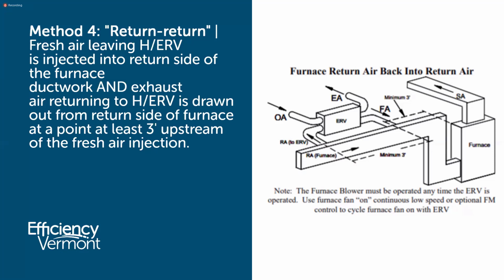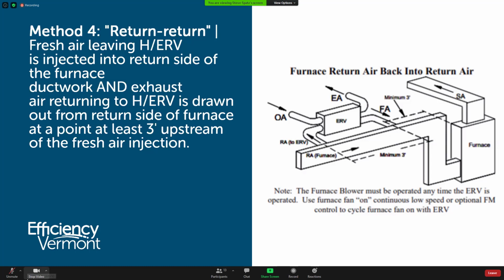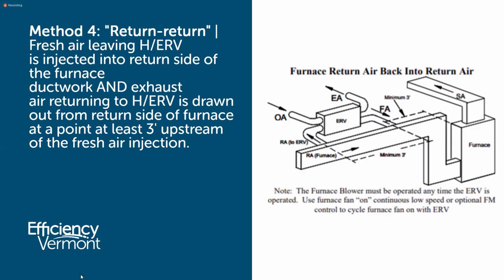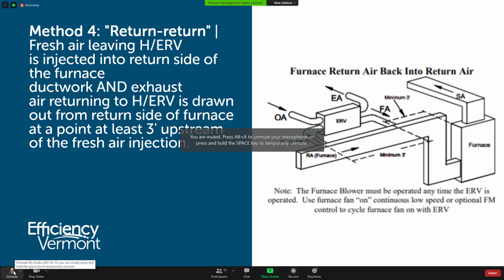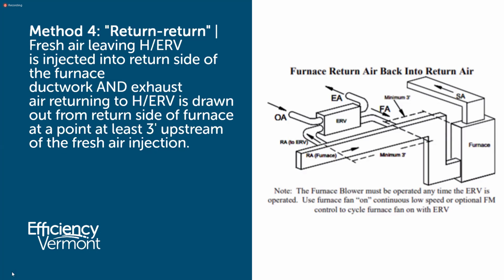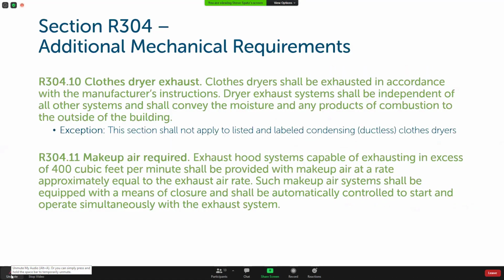So you can't expect everyone to know all of these options in detail, but it's a conversation that you should be having with your mechanical contractor if this is the system that they're proposing. If they're proposing to do a combined ducted system, just be thinking and referencing back to some of these caveats I've mentioned. Is the equipment designed in a way that it's going to work within one of these combined methodologies? And the equipment manufacturers have those methodologies called out in their installation documents also. And also, the balancing of the equipment, the testing of the flows, and options for adjusting flow rates within the duct system. Any questions on that?